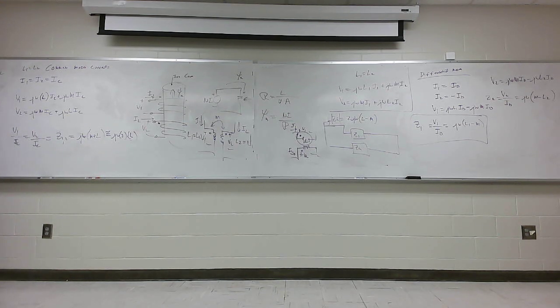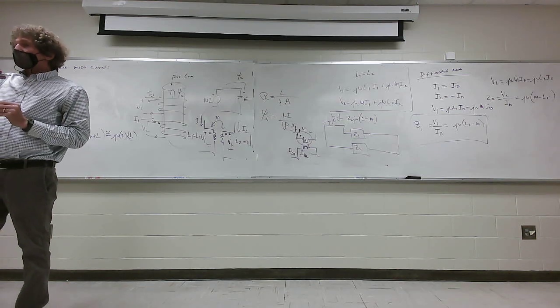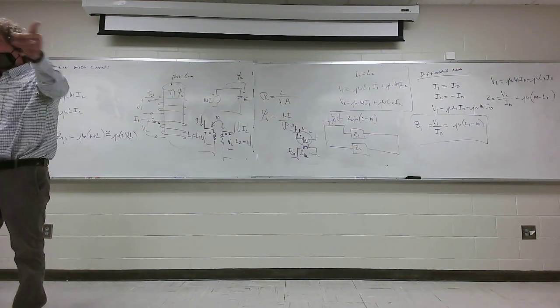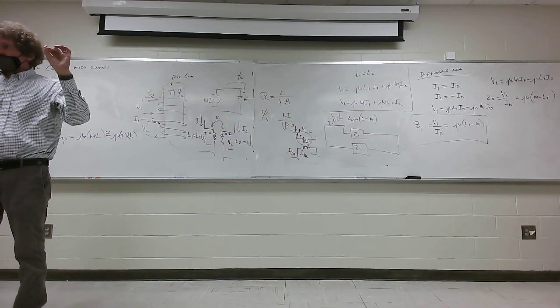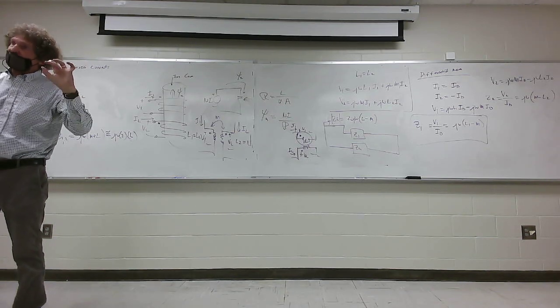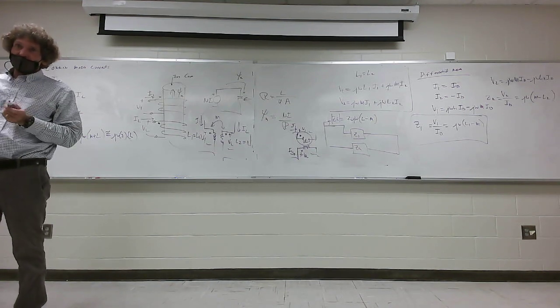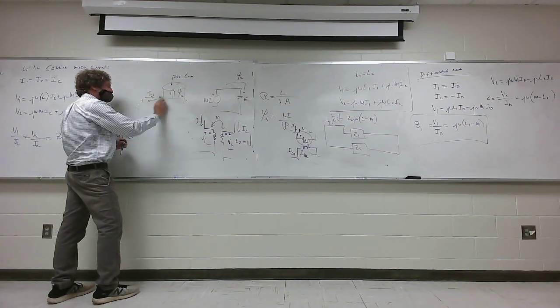Now, in common mode for non-lightning events, lightning is a different story, but if you think about common mode currents, a good question is where do they come from? And you all know if you know what a ground loop is or not. Anytime you have a large piece of wire, either running through the wall or anything like that, and you have a time-varying magnetic field through there, then you get induced voltage. Are you all with me on that? So if you have an extension cord, or you just have a wall outlet there, and it's got 2 wires in parallel running around the room, right? And I'll erase it and show you what I mean right here. Then, interesting things happen.